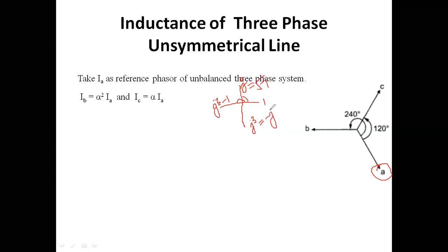So here we consider the j operator for complex numbers, and the angles are equally divided, 90, 90, 90, 90, a total of 360 degrees in four quadrants. Similarly, in the case of the symmetrical operator, the total 360 degrees is divided into three equal parts, 120, 120, 120.